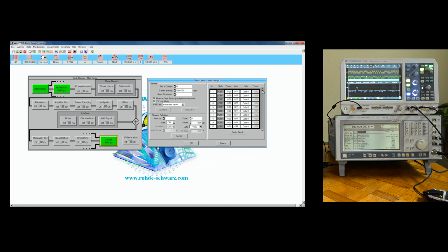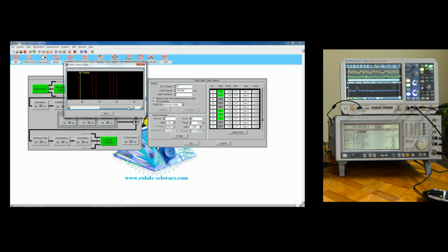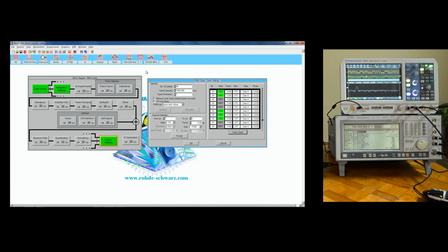I'm just going to turn a selective number of channels on so we can easily inspect it. I'm going to turn on number 19, and then 23 and 24, 3 of them, and then 28, 29 and 30. That means I should have a visible spectral diagram with 1 carrier, 2 carriers a little bit further on, and 3 carriers. And we can look in the domain here. It's in red here. We already see the carriers that are supposed to be there.